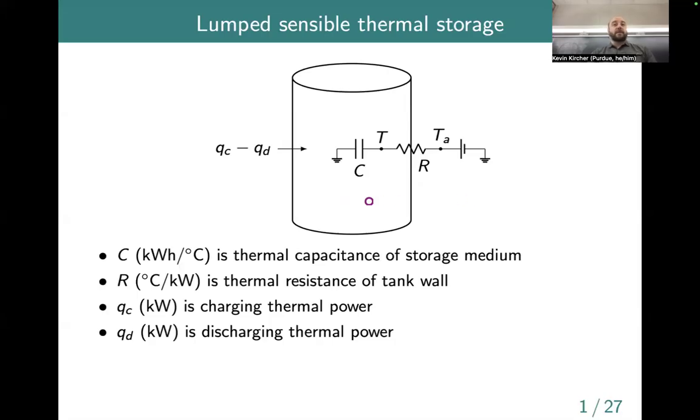Well, a heat pump water heater is going to basically absorb thermal energy from the air surrounding it and inject it into the tank of water. So it'll have to do more work if the temperature gets colder and colder around it. Yes, it would have to work harder and harder. Its efficiency goes down. Also, potentially you don't want the basement to get super cold. If it gets too low, you might have to worry about pipes freezing and things like that.